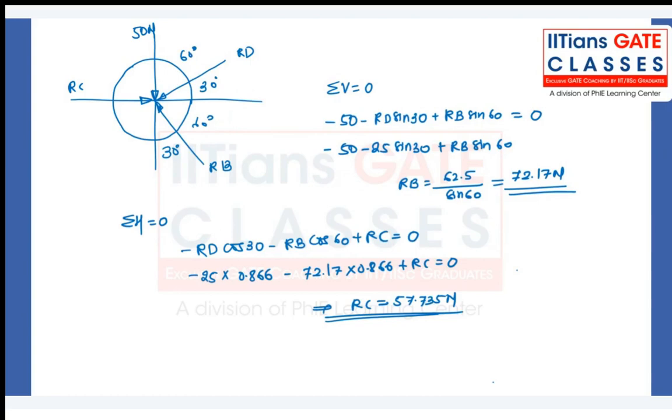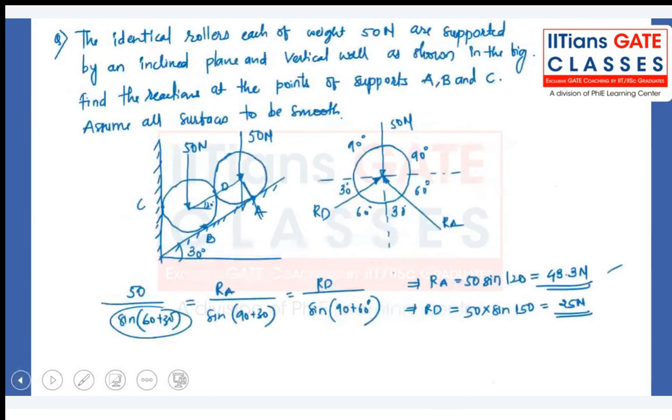See, 80% of the problem is solved once you are able to draw the free body diagram. After that, there is nothing, there is just mathematics. It is just summation of all the forces in horizontal direction, vertical direction equal to 0. And in this case, I applied Lamy's theorem. That is the same thing. Okay, nothing different.